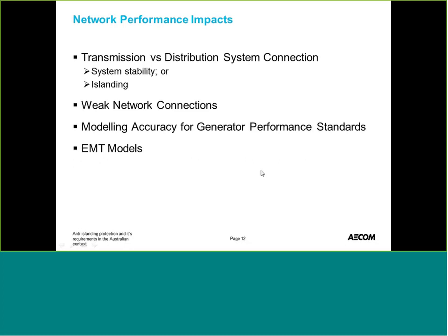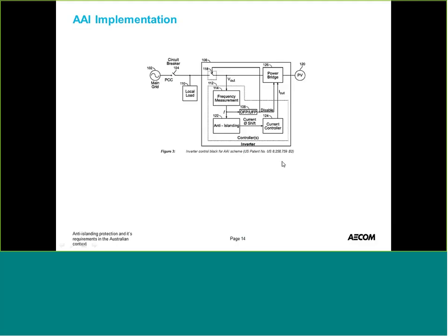So we talked about a PSCAD-based model. These are the EMT models that are required to ensure that the control system is stable. Equipment implementations: if you look at how the scheme is actually implemented, this is the example of a PV inverter. You've got your PV source on the right-hand side. You've got your power bridge, which is your IGBTs, typically carrying out the switching. You've got the voltage, which is used to get the frequency measurements.